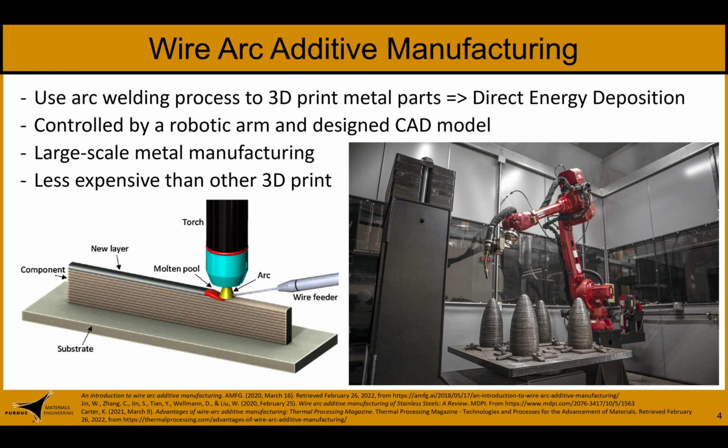However, the challenge of this technique is heat management, as the printing process involves high temperature. The high temperature causes a buildup of residual stress, which is a common problem in metal 3D printing. As residual stress can often lead to deformation in a component, cooling must be factored into the process, or else the residual stress will be a weak point of the structure that could cause failure when using the parts.